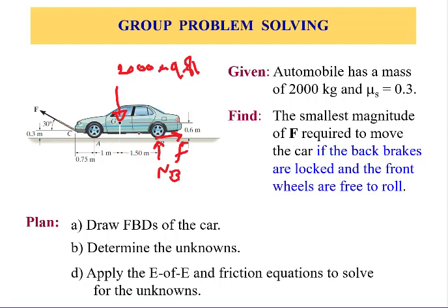And the second set of unknown forces: we have a reaction force at A. However, we don't have any friction force because this wheel is rotating. The rotation of a wheel on a surface doesn't produce any friction force simply because at the contact, the velocity between the wheel and the ground is zero, as there is no relative velocity. So therefore, there is no friction force at this point. So this is the free body diagram, including the force F.